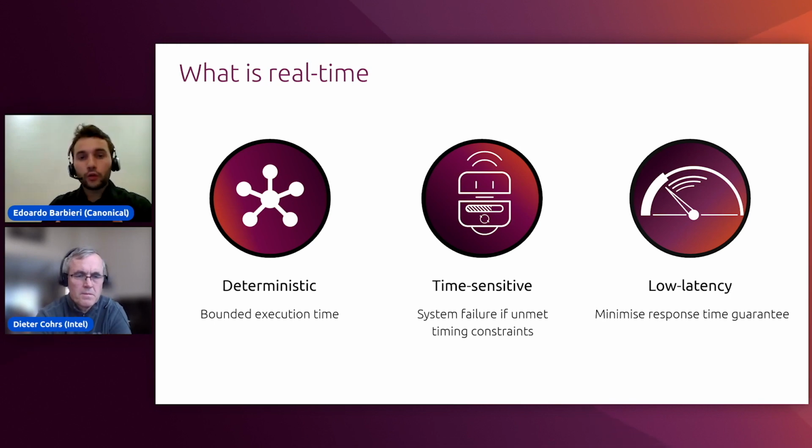Now, I also want to caution the audience around some of the misconceptions around real-time, because a real-time operating system is not always necessary. It sounds promising for something to be real-time, usually because there is a performance connotation that comes with it, but we must really look at the actual consequences for missing a deadline and the latency requirements. Based on that, we should be able to answer whether or not they warrant real-time capabilities. For instance, if a deadline is in the order of seconds, that's likely not going to be missed on a multi-gigahertz CPU with proper tuning.